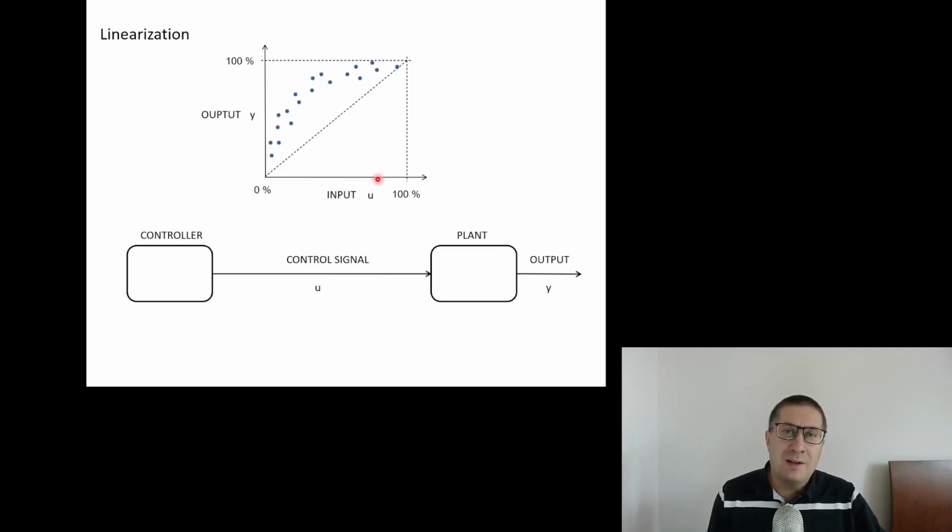But if we open the valve from 90% to 100%, there will be nearly no change of the airflow, maybe very slight change of the airflow. This is this nonlinearity. We change the valve by 10% here, and we saw a huge reaction of the airflow. But if we change the airflow by 10% here on the right edge of the domain, this reaction will be very gentle.